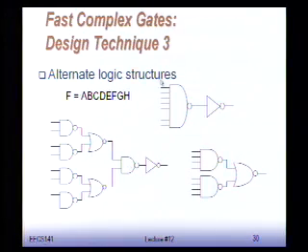And here you can see an interesting analysis, because if the delay was linear in the fan-in, you would always do this big 8-input logic gate, more or less. But actually, sorry, let me take this back. It's not true that if the delay was linear in the fan-in, you would always do a complex logic gate. But anyway, it's even more true that because this 8-input logic gate is not twice as slow as a 4-input logic gate, you don't want to do this.